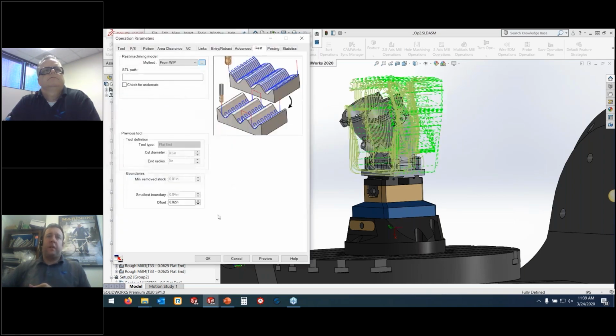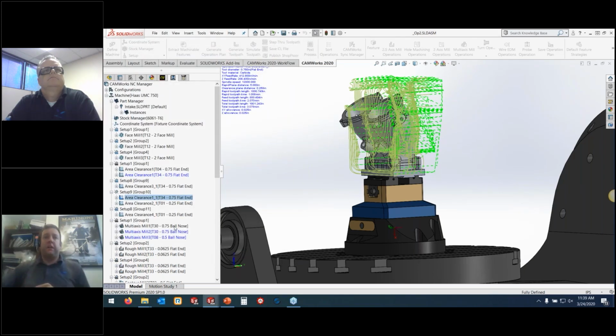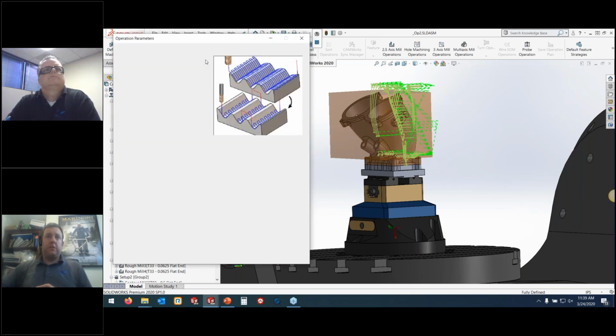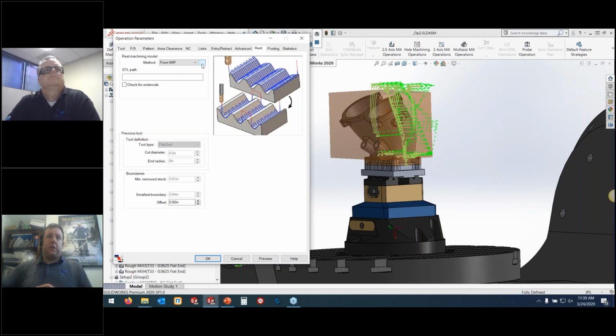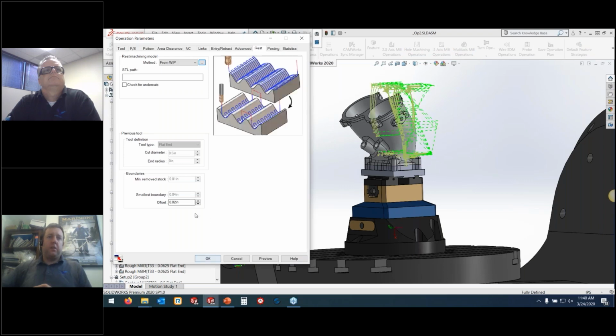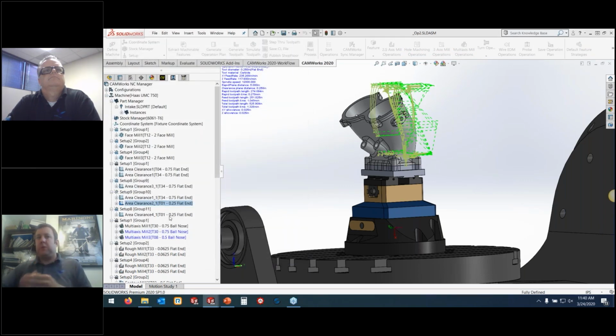Basically, they're just updating the rest machining to this particular stock, which is that STL file that Tim saved out earlier. So we can go through that process, update the roughing, just turning on the rest machining here. And you've got some controls about how much material is left, depending on the different pattern types that you use. You can come in here and control how much material it thinks there is left. If you're getting too much code, you've got different options in there.